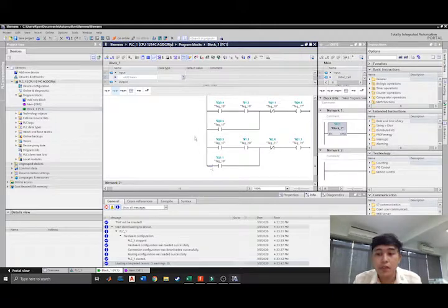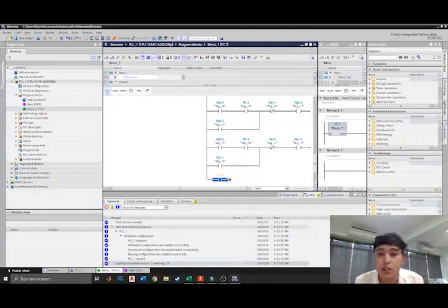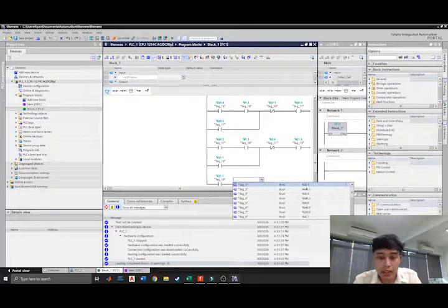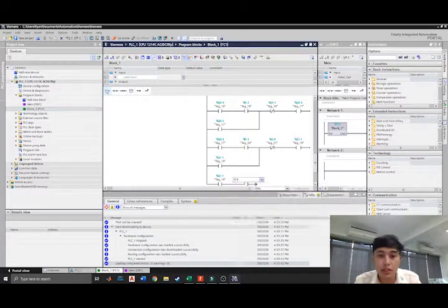Then for the distributor cylinder, let's place a branch and then an opening condition, which is the starting of the cylinder, and another one for the metal sensor with the address of I0.6, and then a normally closed for the photoelectric sensor to stop the conveyor.